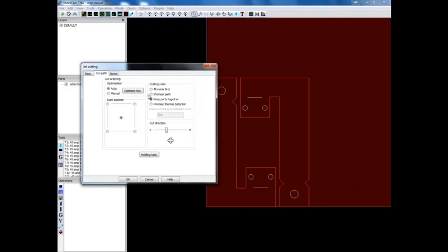It is far superior than trying to do all your interior cuts and then come back and do your exterior cuts. The reason being is if you have a problem at any point in time in the cut, you can end up with the whole sheet full of holes and no way to accurately cut the exteriors. This way, if you cut one part at a time and there's an error, you only make that error on one part. And then start position I will set down here.